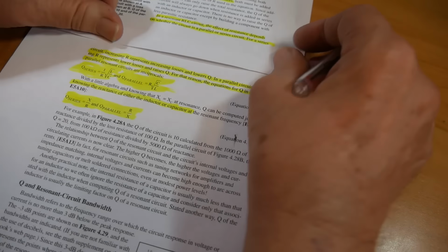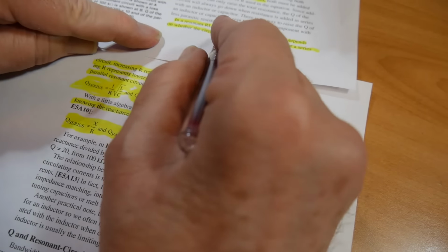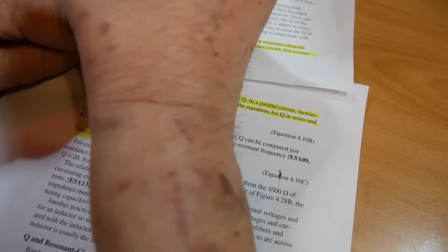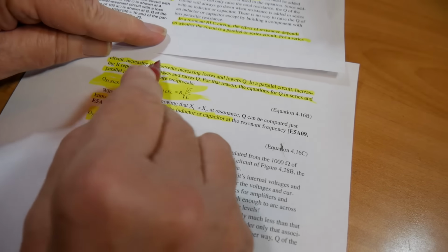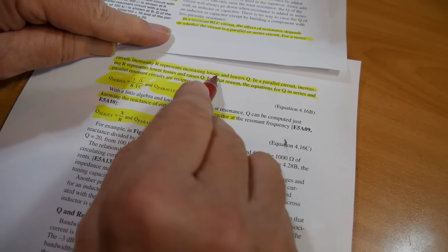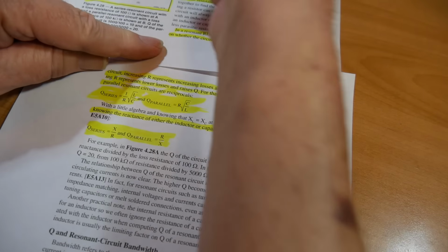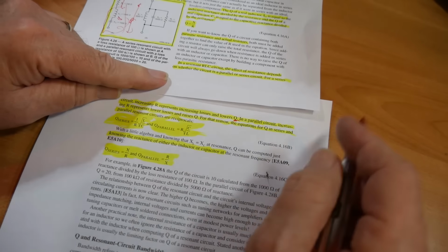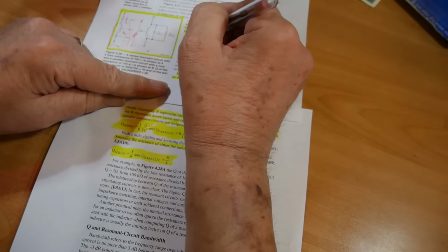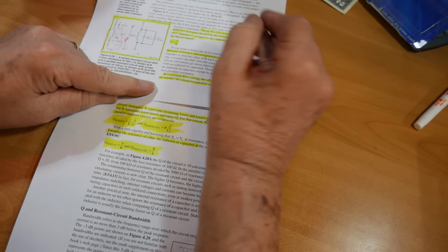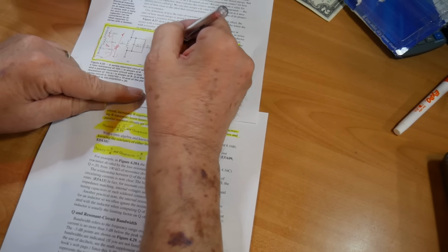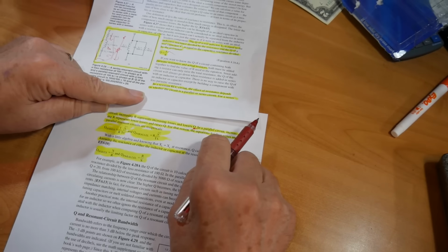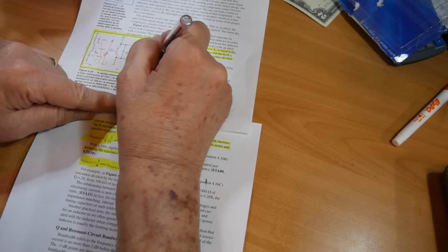Now, let's look at the overlap of the pages here. In a resonant RLC circuit, that's these two. This one's series, this one is parallel. For a series circuit, increasing R represents increasing losses, right here, and lowers Q. Q, for an inductor or a capacitor, is the reactance divided by the resistance.